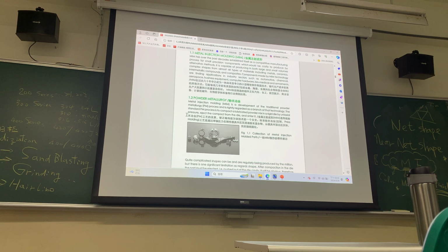Then if we add the metal powder inside, the plastic is only 10% by weight. Then the melting is the same, but the cooling down is quicker. Why? Because the thermal conductivity with the metal powder is higher, so the heat goes away easily. So this part is easy to cool down. It's very interesting, it's different too.